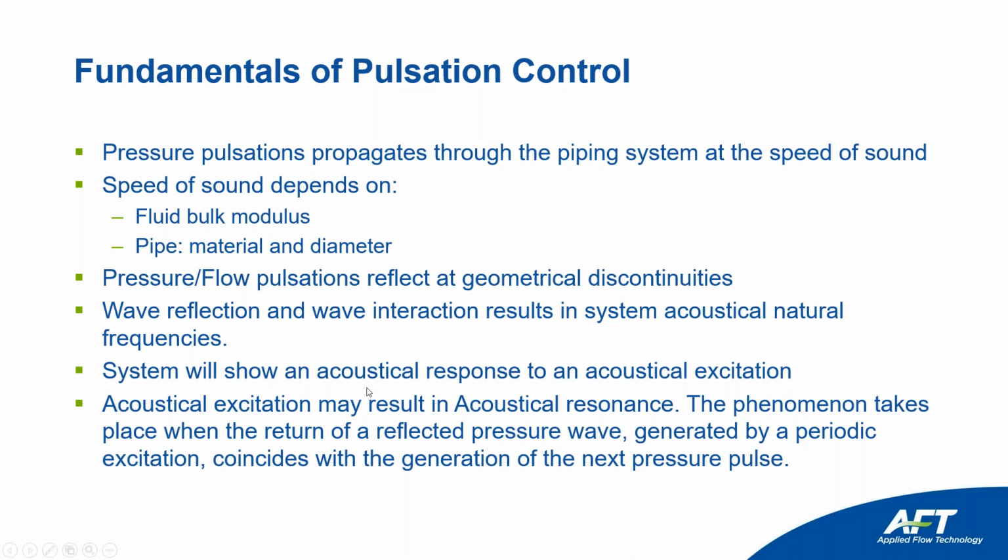The system will show an acoustical response to an acoustical excitation. We're going to calculate some natural acoustical frequencies, but not all the frequencies will show, and it will depend on the acoustical response of the system, depending on the acoustical excitation you're applying. Acoustical excitation may result in acoustical resonance. The phenomenon takes place when the return of the reflective pressure wave generated by a periodic excitation coincides with the generation of pressure pulsation.